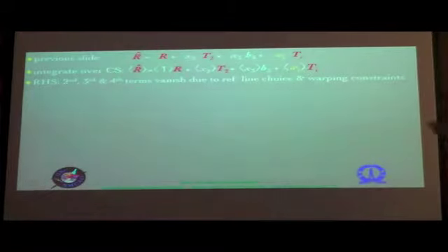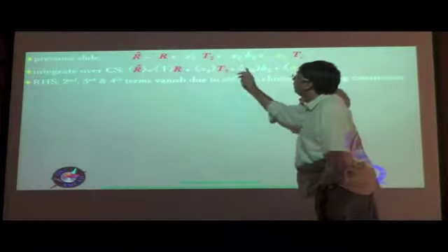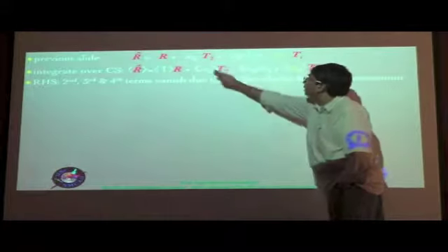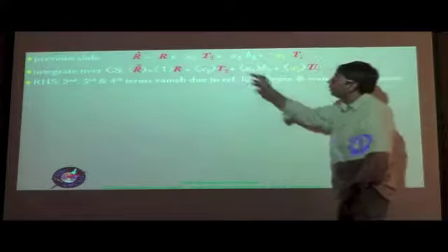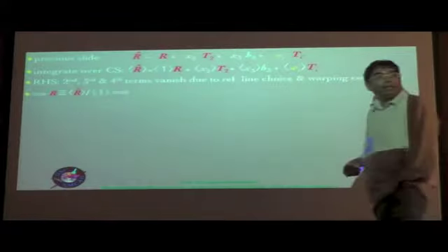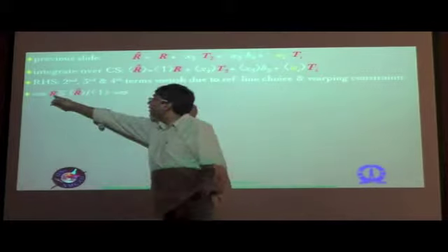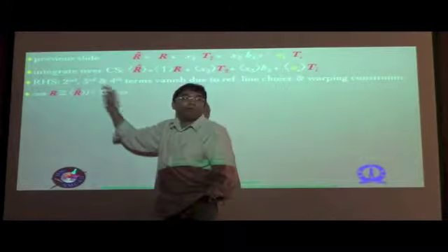So once again, the second and third terms, because of the choice of the reference curve as the locus of the area centroids, go to 0. And because of the choice of the warping constraint, this goes to 0 as well. And you have an exact analogy with what you had in the undeformed configuration, in the deformed configuration as well. So that is, R is equal to the average of R hat.